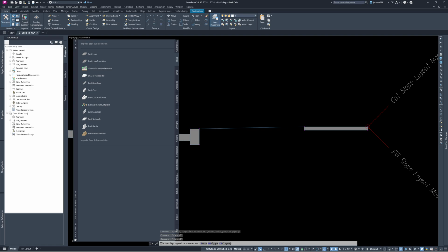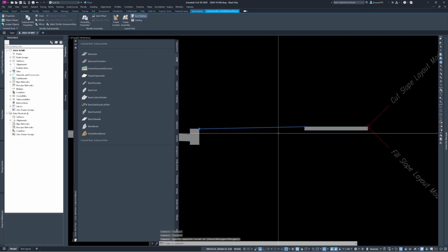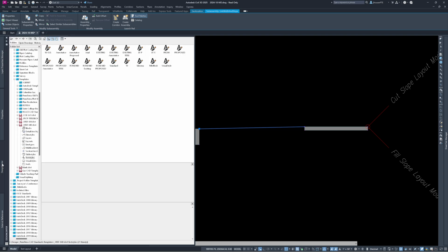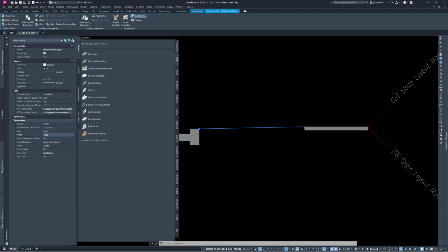This is just our link. Now, if this is a 50-foot cartway and we want the curbs on the inside, so essentially we'd have to subtract 12 foot minus 5 foot minus the 0.875, all from the 25 foot, and that leaves us with a width of 7.125. I know it's not the most common width, but that gets us to the final product. And we want our 2% slope going up away from the crown. So that gives us our lawn area that we typically have.